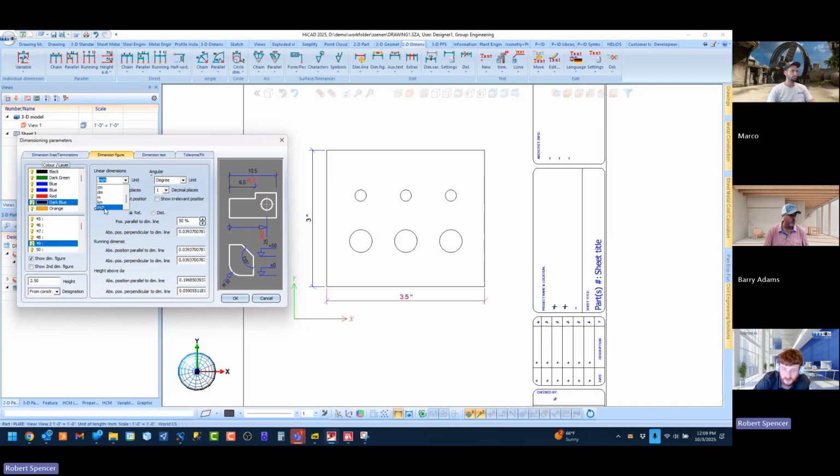to whatever you need. In 3D, we can show inch in different fashions, like with inch feet or just inch, or show it with tick marks, one tick versus two tick, decimals, fractions. Arrows? We got a lot more in 3D settings. These are 2D settings, a little bit less, but still there's quite a bit here. Decimal places. So you know, right now I have 1, so it's showing 3.5.